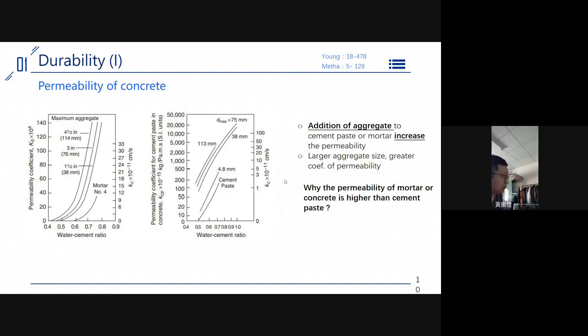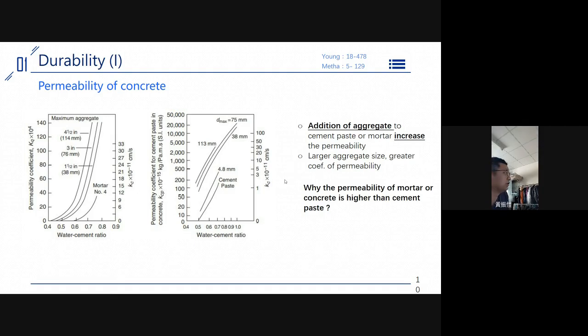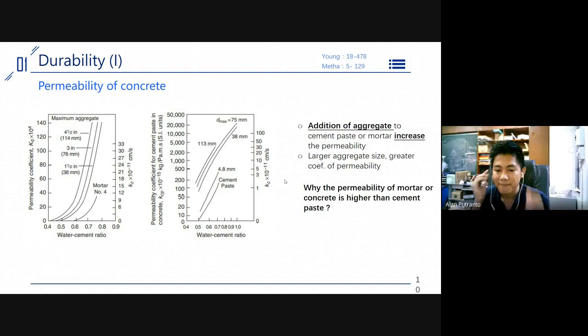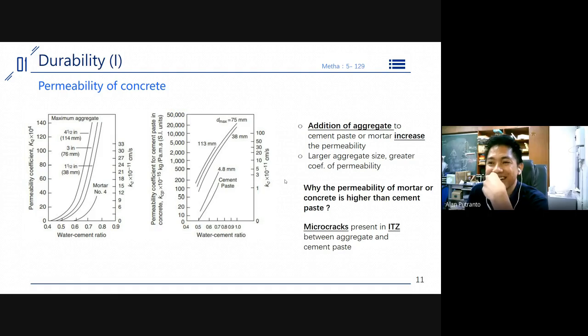So the professor mentioned, as you say, porosity, which is a big concern in the permeability of concrete, and also whether the pores inside the porosity are connected or not. And as the senior mentioned about the ITZ, the interfacial transition zone, that's also a big issue here, because the cracks that happen in the ITZ are a really big issue. And in the end, the professor said if you don't have enough time today, it's okay, just continue. We can find another time for you to finish. So maybe we should just continue.